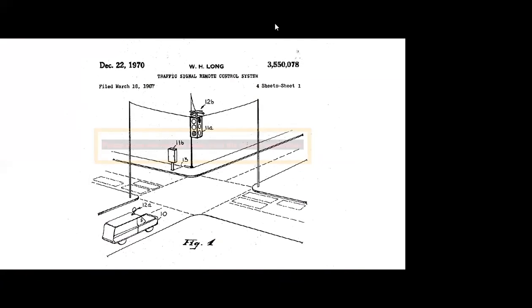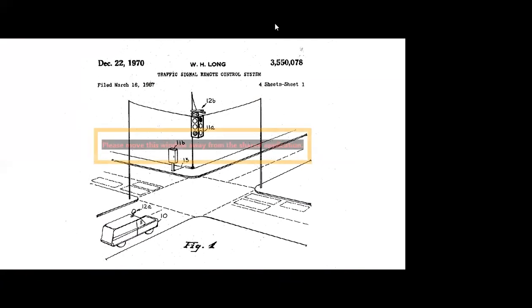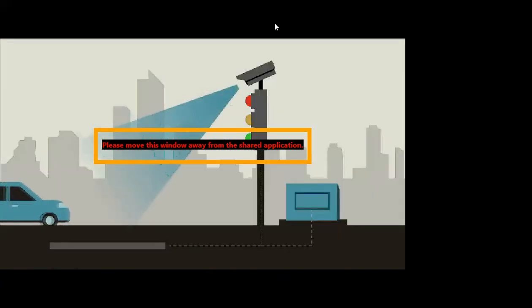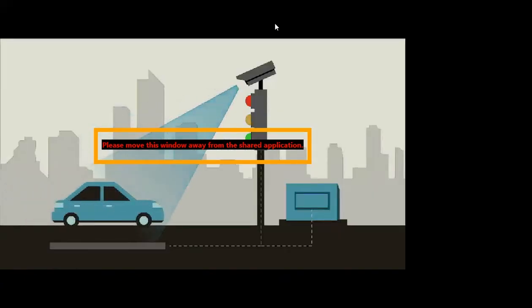Actuated signal control is the term we use for signals that can receive input from the outside and use that information to make decisions about light timing and sequence on the fly. These types of signals rely on data from traffic detection systems. These sensors can be embedded cameras or radars, but most commonly they're inductive loop sensors embedded into the road surface. They are essentially large metal detectors which simply measure whether or not a car or truck is present, sometimes to the annoyance of bicycles, scooters, and motorcycles that may be too small to trigger the loop.